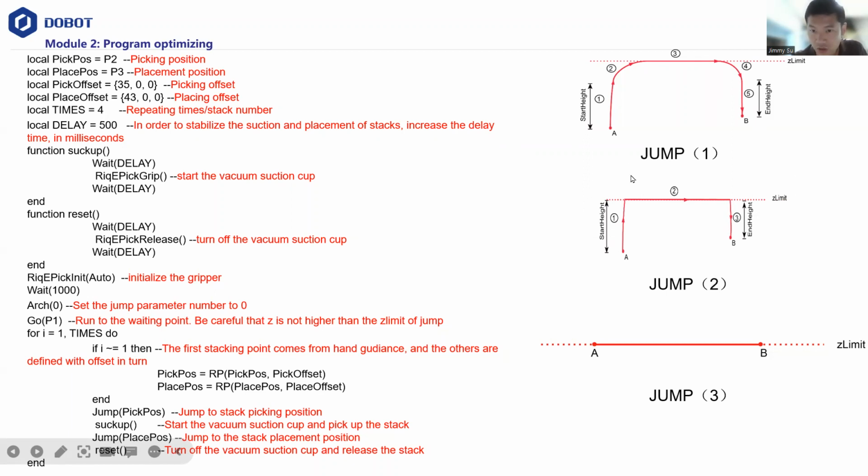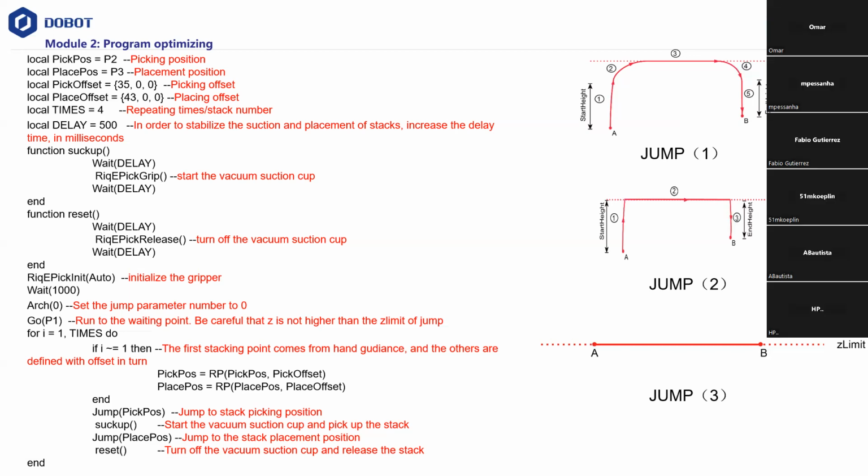And it's also really important to look at number 2 and 4. This is also for optimization. When you start your project, you can make the robot slow, right? You can test it slower. It's okay, just be safe, pick something up, move and drop it. But after you figure out the whole process, you want to make your beat faster, right? You want to optimize pick and place from 5 seconds to 2 seconds. And how do you do it? You can optimize on here.